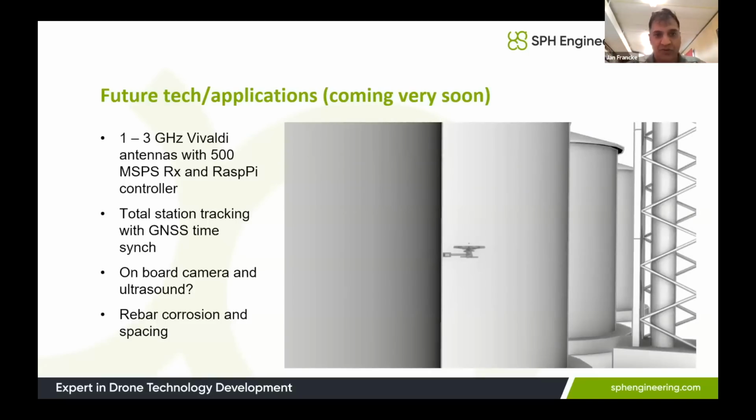I am going to touch very quickly on a new type of GPR that's being developed, and that's high frequency systems that have stingers that essentially can be mounted on a drone, either up or across, and that could go up and down tall concrete structures to map not only rebar depth, but also corrosion and all that sort of stuff that we do currently with rebar concrete as it is.